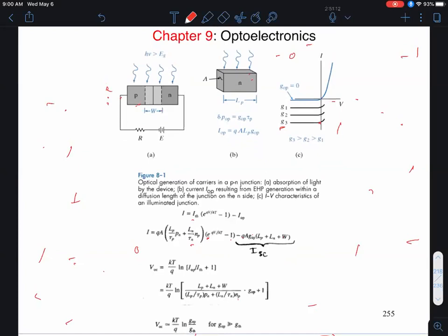So last time we discussed the fact that all kinds of optoelectronic devices could be made up of a p-n junction under illumination, simply depending on the quadrant in which you operate it. If you operate in quadrant 1, you get forward bias devices, and under those conditions, the injected electron hole pairs can recombine, especially if it's a direct bandgap semiconductor, and emit light as in a light emitting diode, or if the light comes out in phase rather than in random phase, you get what's called a laser.